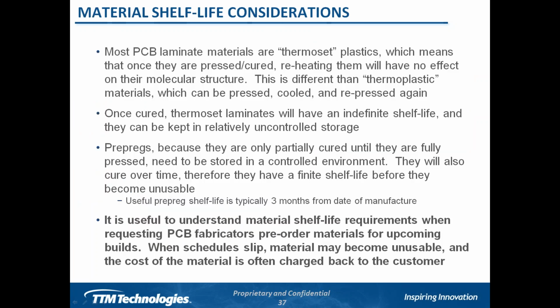Now, a quick note on shelf life of these materials. We do get asked about this quite a bit. Most PCB laminate materials are thermoset plastics, and this means that once they are pressed and cured, if we reheat them, it has no effect on their molecular structure. So you can't reheat them and have them melt.